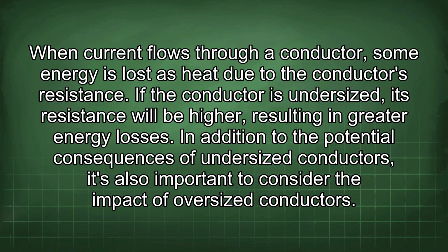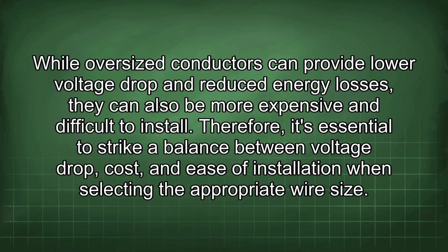In addition to the potential consequences of undersized conductors, it's also important to consider the impact of oversized conductors. While oversized conductors can provide lower voltage drop and reduced energy losses, they can also be more expensive and difficult to install. Therefore, it's essential to strike a balance between voltage drop, cost, and ease of installation when selecting the appropriate wire size.